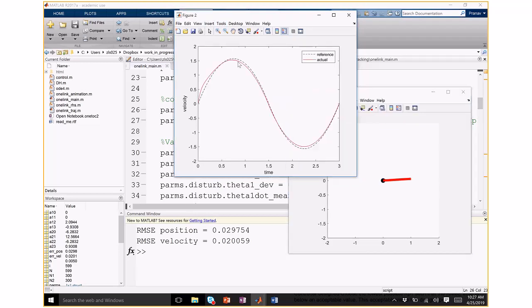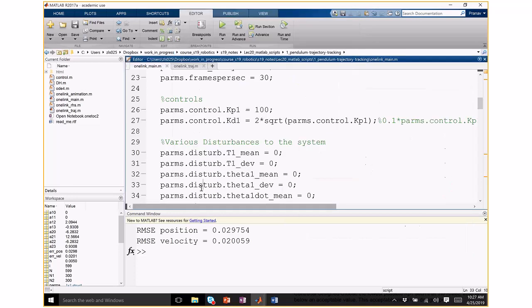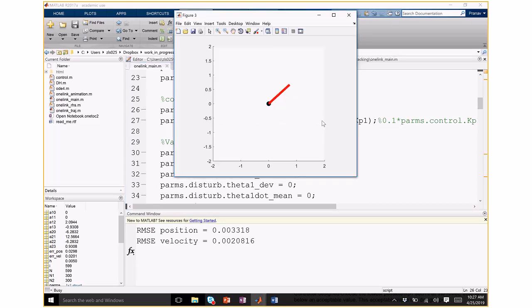So that's better. You can see there's an error. That's why this is not equal to 0. If it was perfect, it would have been 0. This is the velocity as a function of time, position as a function of time. So you could technically go up on the gain here, and at some point it'll break. It'll break not because of noise, there's no noise, but because my integration has certain tolerance. So I think this is the most you can go.